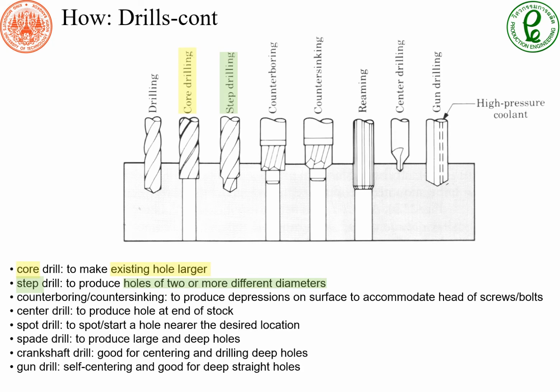So there are a variety, as I said, of drills for specific purposes. The core drill is used to make an existing hole larger. So if you have a hole and you want to create a larger hole, we can use the core drill. The step drill is to create a hole with multiple diameters, with different diameters within the hole.